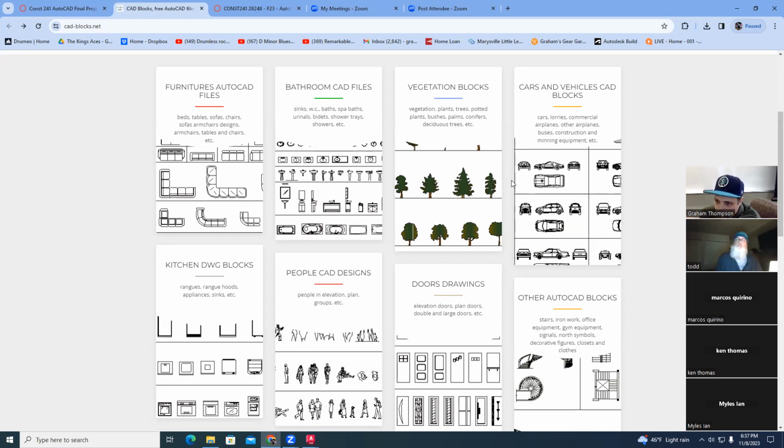And then you would also have a framing plan. The framing plan would show the wall without the gypsum on the front, and you would see the studs. So you would see every stud, whatever width, depending on if you're doing metal studs or wood studs, your 16-inch center to center framing, whatever it is. And then you would show all of your framing for any window cutouts, any doors. Yeah, so drawing that framing is what I'm trying to do.